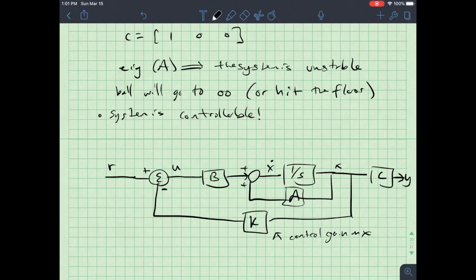All right, and if I solve this out, I would identify that I actually have a small problem, and so what I might do is insert a gain, which I'll call N bar. I might insert that right here in place of just an empty line here, and that's just to make sure that we're getting the appropriate gain in the system. I'm eliminating any scale factors that might be there.